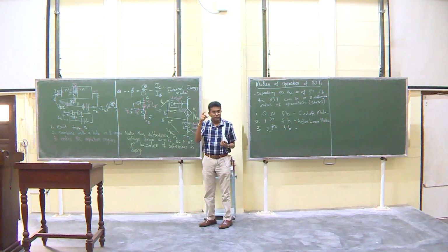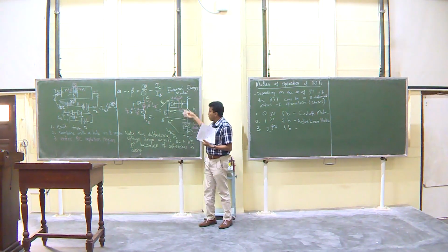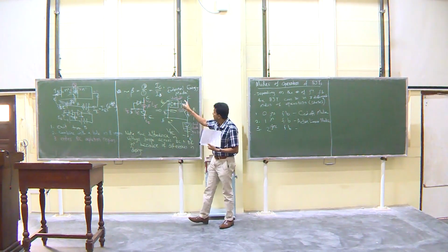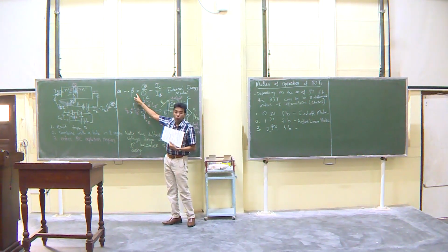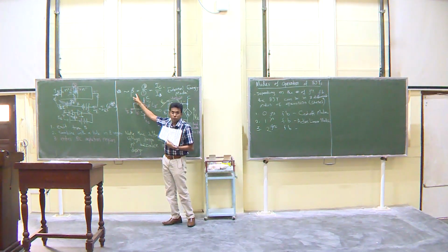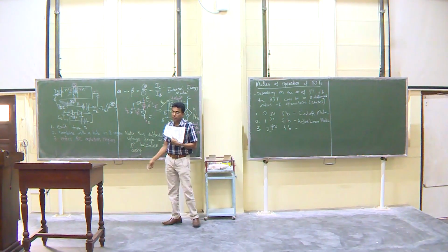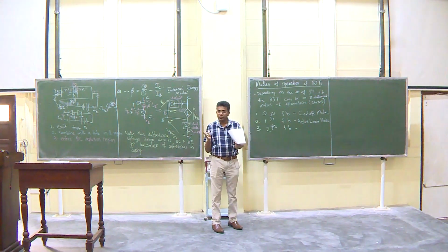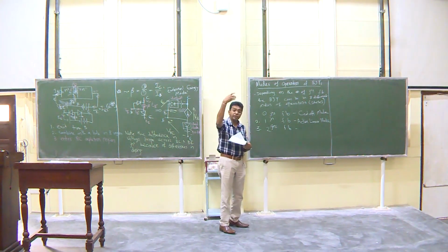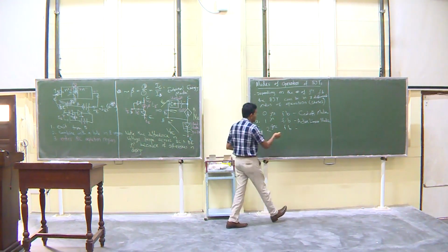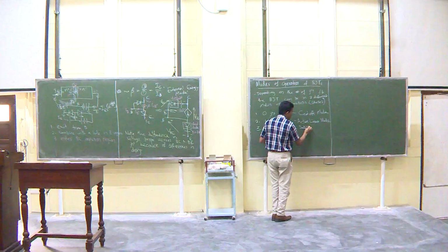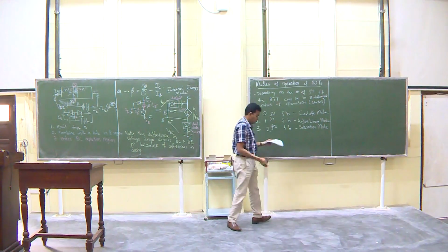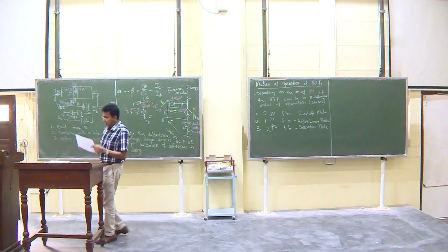The current here will also be determined by the external circuit rather than this expression. This expression will no longer be valid when both the junctions are forward biased. So, it behaves differently, and the behavior will be determined by the external circuit. We call this the saturation mode. So, those are the three different modes.